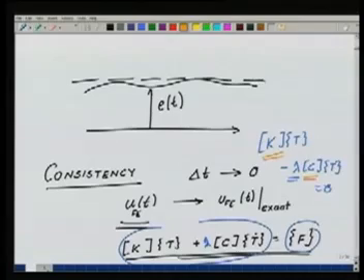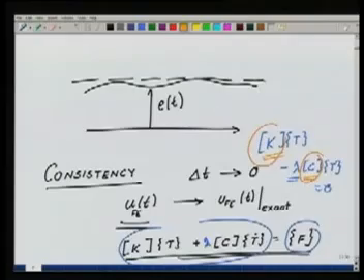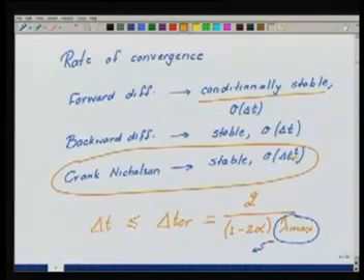As we keep adding more and more elements to the finite element mesh, this lambda max is going to change, and depending on that lambda max, the delta t critical is going to change. So for a fixed mesh, there is a particular lambda max that you get from the stiffness and the C matrix, while if you change the mesh, this is going to change. This is something one has to keep in mind when doing temporal solutions: the selection of the time steps has to be done in a proper way.